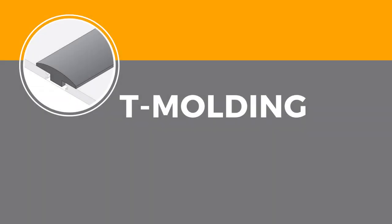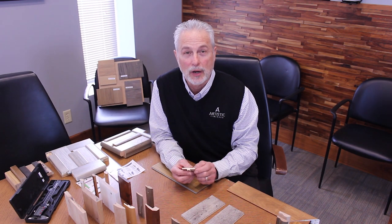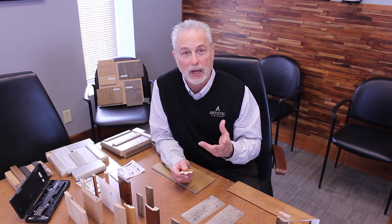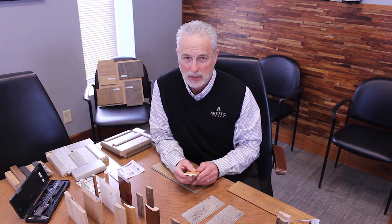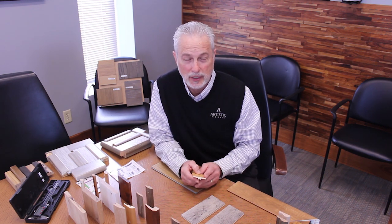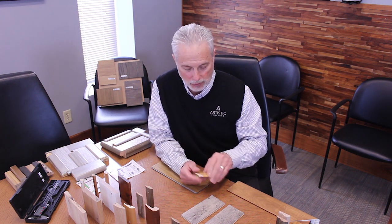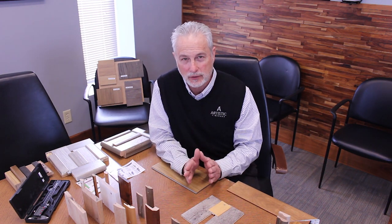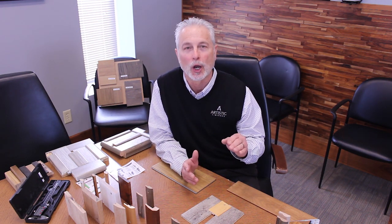T-moldings have long been one of the staples of the industry. They are used where you have two surfaces, hard surfaces, and I emphasize hard, of equal height. The T-molding should not be used as a reducer. So if you have any discrepancy in height at all, we'll talk about reducers and the versatility of them when we get to that section. But the T-mold should be used where you have two floors of equal height, where you want to have an expansion or a transition that will create a nice finished look.